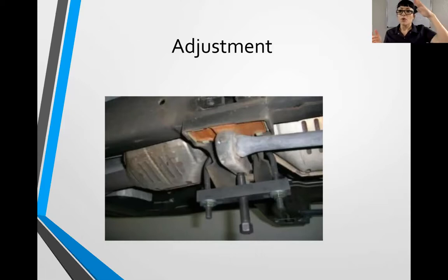Simply that will allow your vehicle to change ride height and spring rate. So you want to be careful with that. It's kind of nice because from the factory you have adjustable ride height, but you also want to take care not to adjust it extreme in either direction, all the way up or all the way down, because you're gonna lose either travel, or it's gonna be a very, very stiff spring.